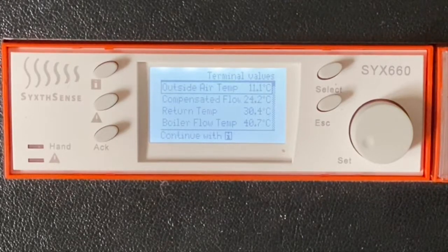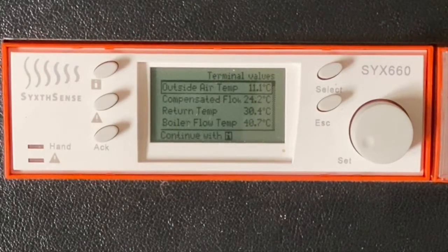Obviously, just make sure that they're all working prior to powering up the controller's outputs in terms of the mains voltage signals. You want to make sure that all the wiring is correct before you permanently power up the device, especially with mains power on the outputs. So, okay.